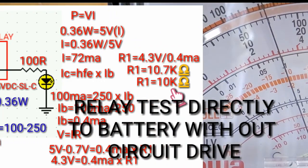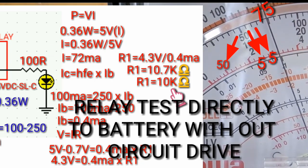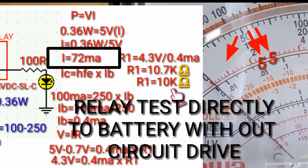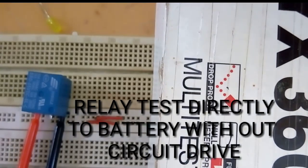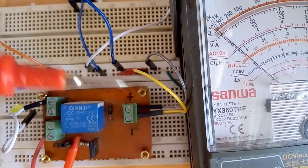Now, let's compare the current flowing through the relay switch circuit. From the calculation, the current is 72 milliamp, and from the tester, the current is almost 75 milliamp. So the current from the calculation and from the tester is almost the same. Now, let's check the base current of the BD139.